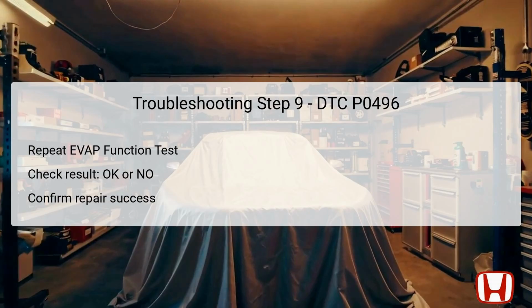It's crucial to check the result meticulously, as an OK result indicates successful troubleshooting, while a not OK result suggests that further inspection is needed. Should the test return a not OK outcome, you will need to check for any poor connections or loose terminals